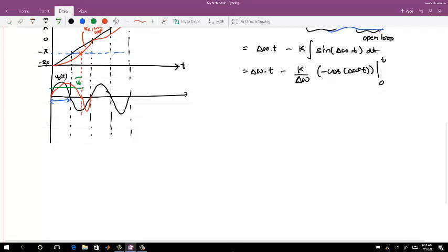So the whole idea behind this is to tell you how you acquire that voltage. You get an average phase error which is non-sinusoidal, which develops an average DC voltage. And if that DC voltage is large enough for the oscillator to lock to a frequency, then good. And if it doesn't, then what happens? You will see that.